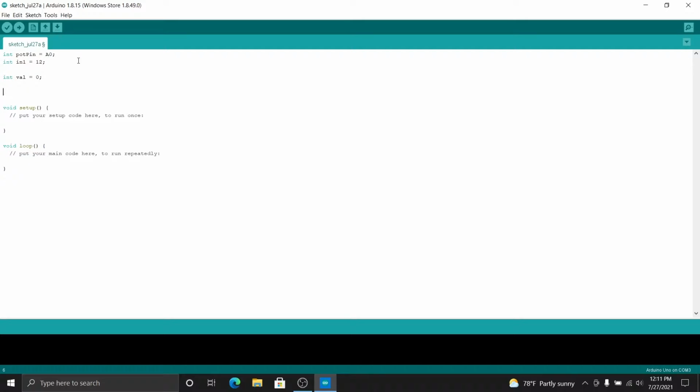And then we're going to create two more variables. One we can call threshMin, which is going to be the minimum sensor reading that we want for our potentiometer. So I'll do 200. And then we're going to do threshMax, which is going to be the maximum number of our sensor reading for the potentiometer to work. And I'll do 300. About 100 difference is a good number. Now, of course, if you have a smaller number, it's more accurate. And if you have a bigger number, then people can be less accurate.